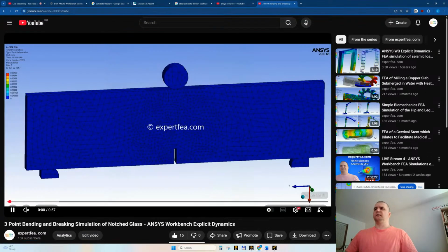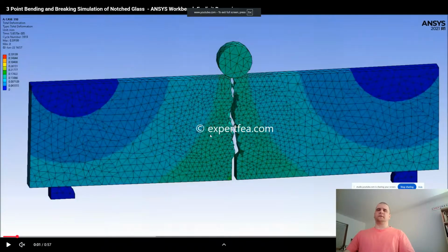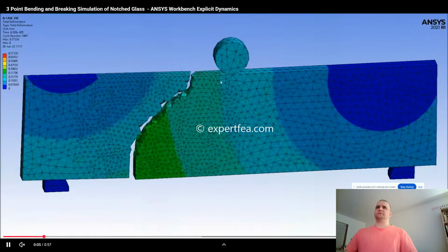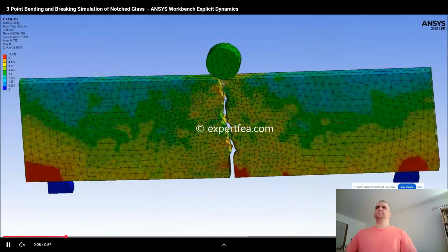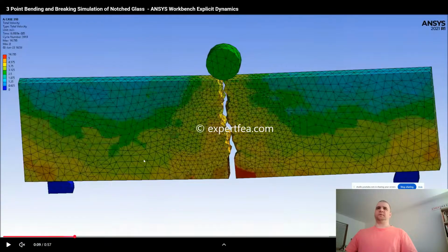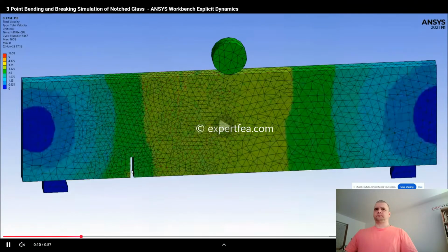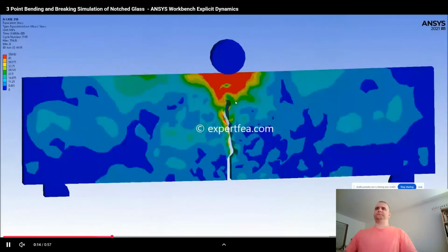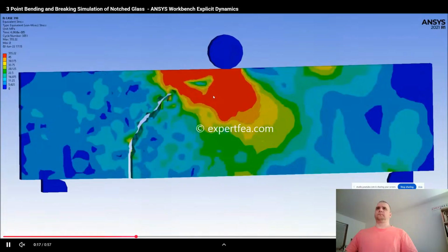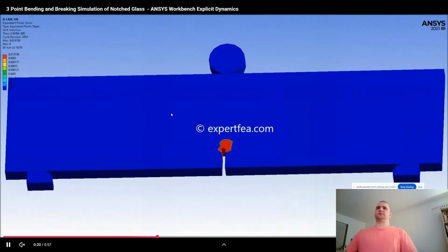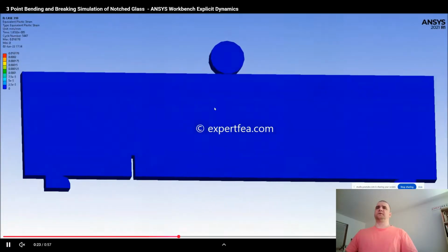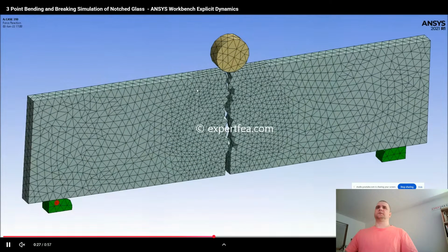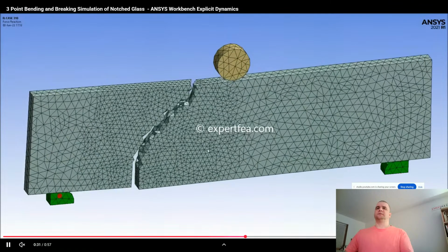This is something kind of similar, and you can see tetrahedral mesh, and this is glass. It's also brittle fracture, but it's glass. They have two scenarios, a notch here in the middle and one displaced, and you can see how the fracture path is formed with classical traditional Lagrangian mesh. And in a few minutes we are going for the SPH, the smooth particle hydrodynamics approach with the small spheres.